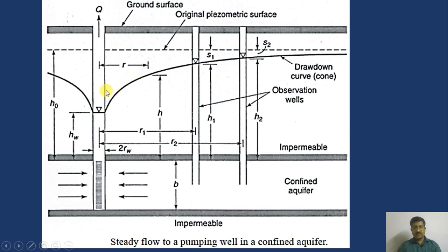The areal extent of the cone of depression. At a constant rate of pumping, the drawdown curve develops gradually with time, so the water table elevation at a given location near the well changes with time. On prolonged inflow of groundwater from the outer edges of the zone of influence, the drawdown operates under steady flow conditions.